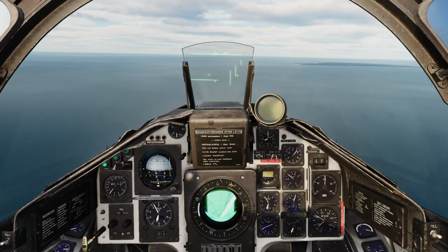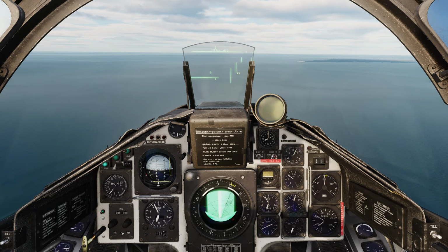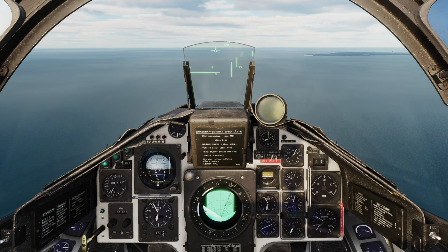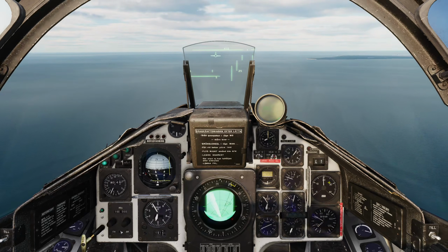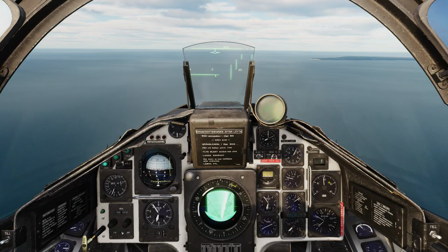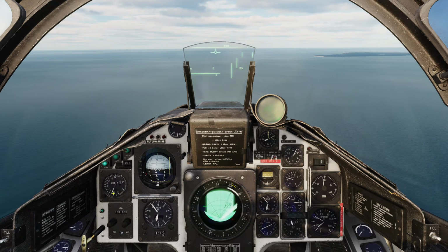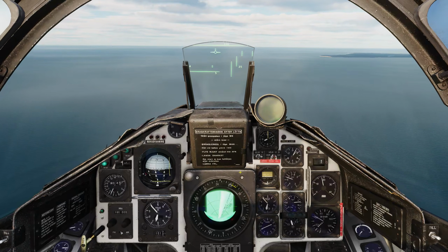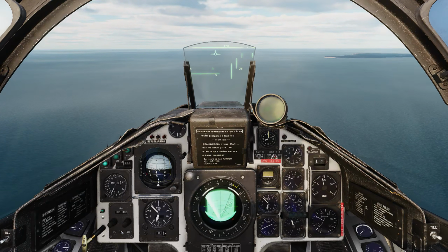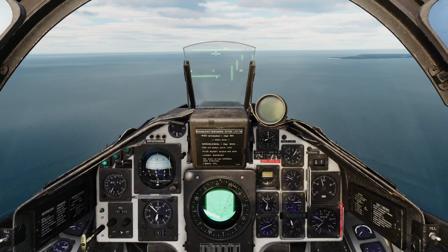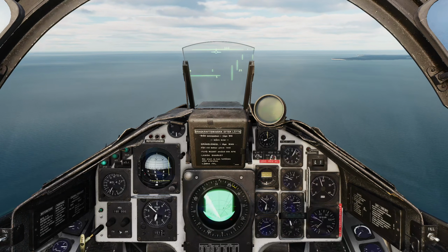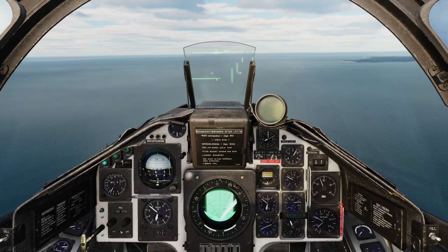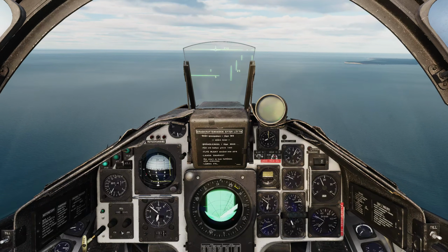During the approach, we're monitoring our distance to the airfield. We're at 20 kilometers now, and fuel remaining. I'm at about, what is that, 40%? I've got about 40% fuel. That's perfectly fine. There we are at 550 kilometers per hour on the airspeed indicator, so I'm throttling up just a touch. Important thing to note during the landing is that when you lower the gear, the Viggen at that stage automatically deploys the flaps. Those two systems are linked. So just be aware that when you extend the landing gear, you're going to get a little bit of a balloon. That's fine.